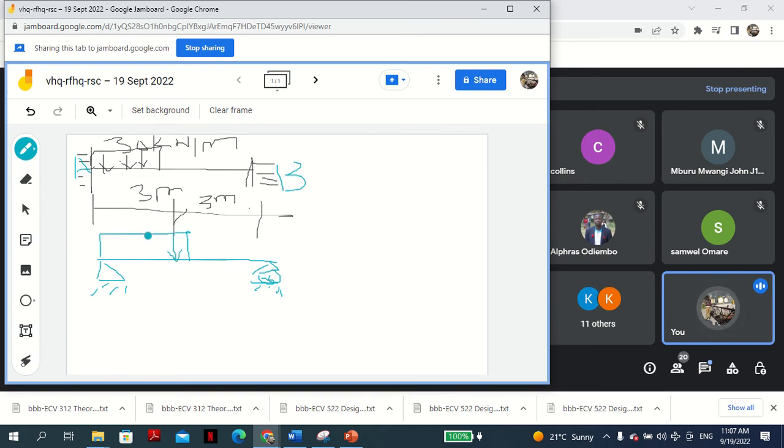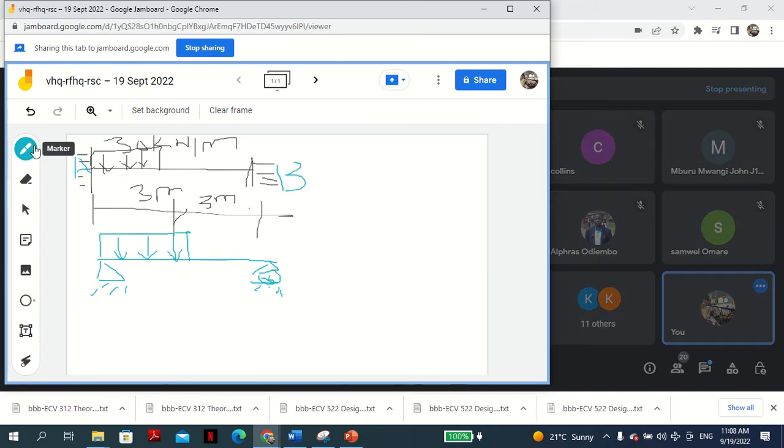If there are no externally applied horizontal loads with the pin, then the horizontal reaction on the pin is zero. It would give you trouble to solve. But even if there are two pins and you understand that principle, you can still solve. But strictly speaking, this is the way to make it statically determinate.